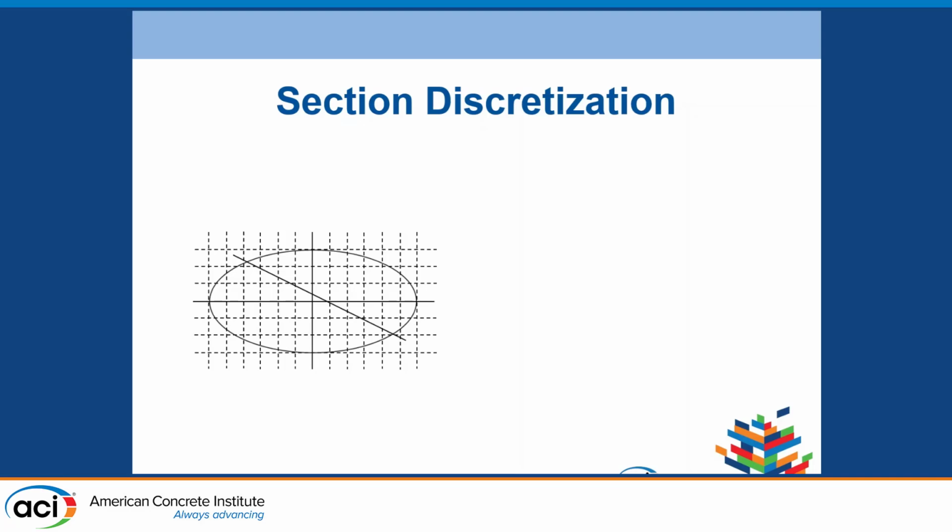Now, the problem with discretizing it this way creates some irregular elements around the edges. So you can have sometimes triangular, sometimes trapezoidal elements, sometimes even other shapes. And that would complicate the algorithm a little bit and make it tedious to work out. And then also the execution time will not be very efficient.